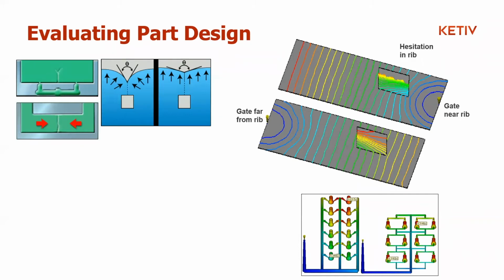When you have a mold with several parts like this one, you want to make sure that each of the parts in there takes pretty much the same amount of time to fill up and has the same amount of pressure, etc. That's one of the primary ways to ensure that the parts are as close to being identical as possible.